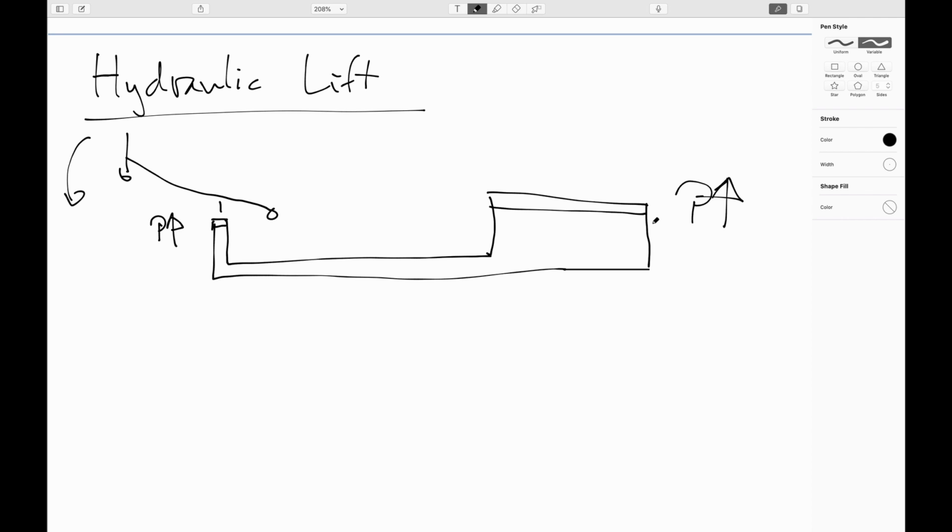So usually the idea with a hydraulic jack is you're just trying to barely get the tires to clear off the floor. So you don't have to move this piston very much. You'll have to move that a fair amount. So the work done here and the work done there are the same. Small force, big distance. Big force, small distance.